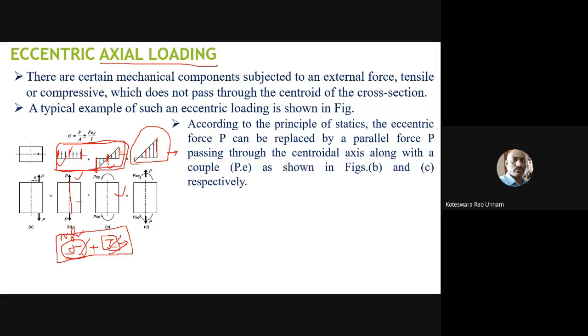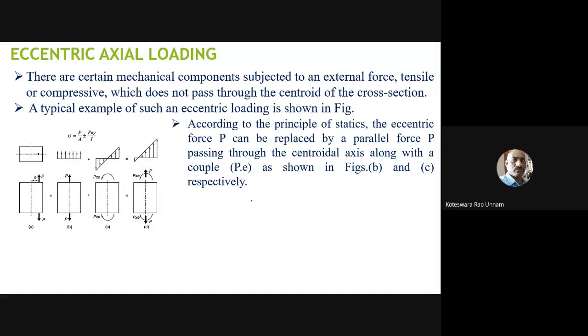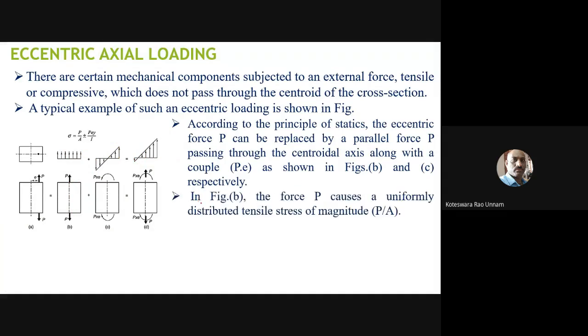In the case of axial loading, this principle is valid only when the load is axial. Therefore, you can use the principle of superposition to find the resultant stress. That is what I have written here. Figure A is the axial loading case. In figure B, the force causes a uniformly distributed tensile stress of magnitude P by A. We know this for this figure.